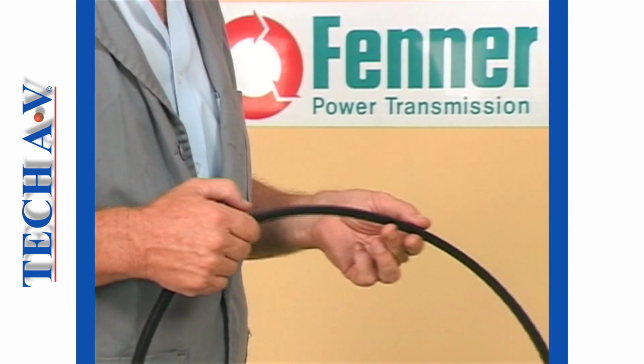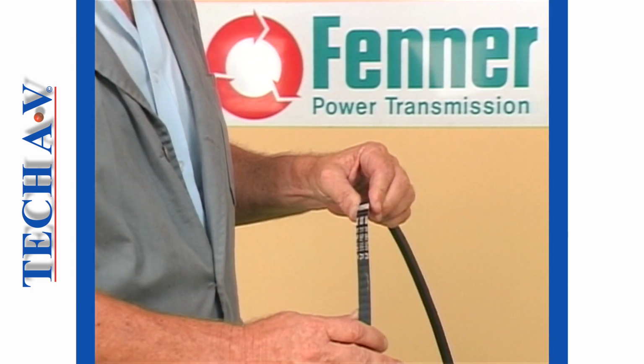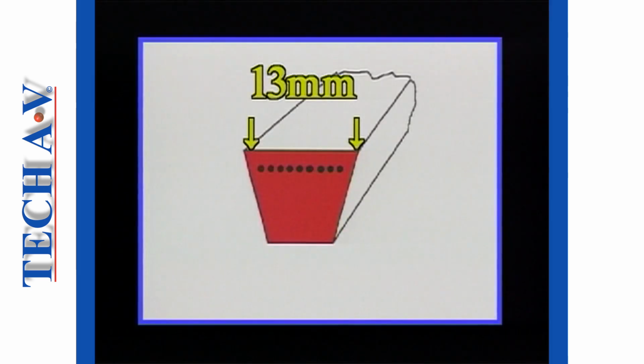All manufacturers of quality belts provide written identification of the belt type on the actual belt. On this belt, you can clearly see that it is an SP-A type. The letters 13N denote that it has a top width of 13 millimeters and that it is of a narrow section.